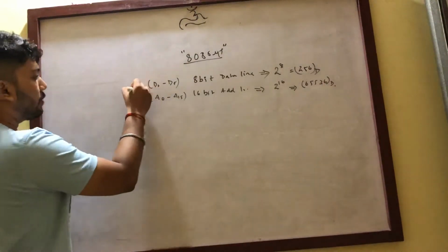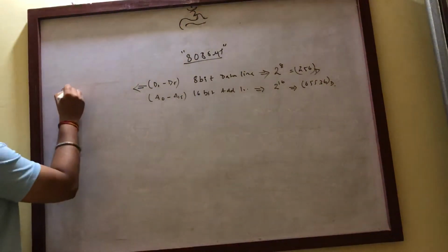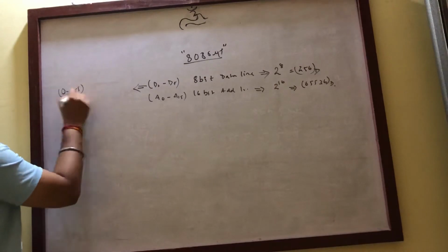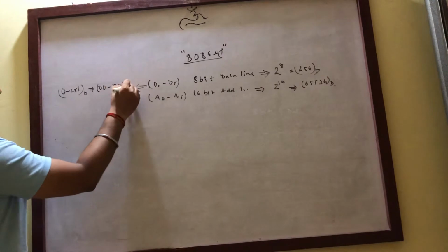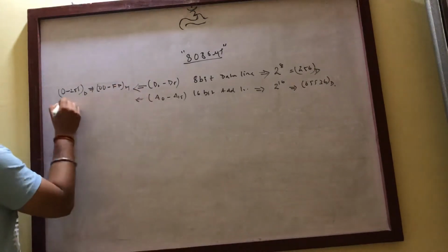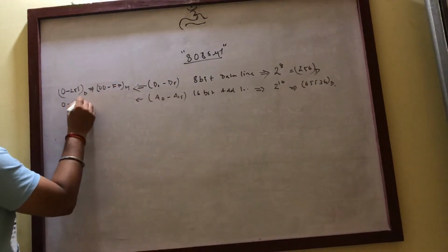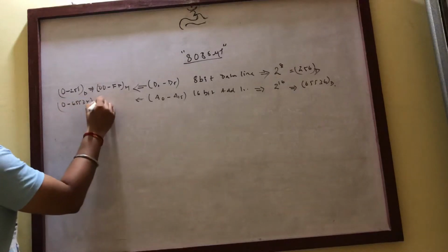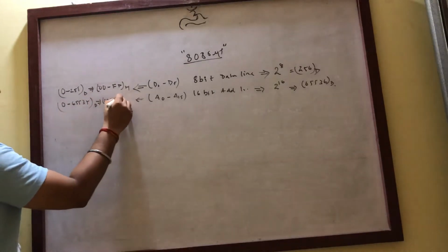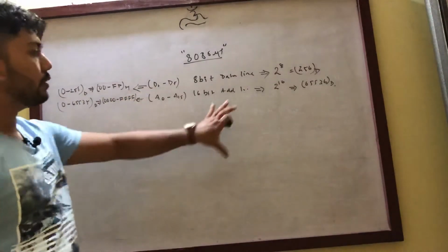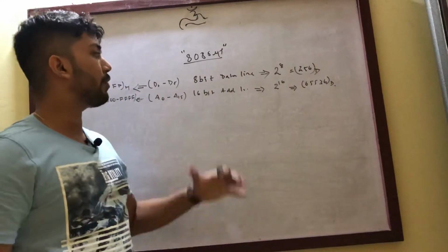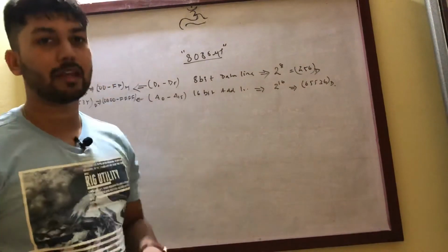So coming to its range, for data it is 0 to 255 in decimal, and that is 00 to FF in hexa. Similarly, for addresses it is 0 to 65535 in decimal, and 0000 to FFFF in hexa. So this is the basic thing about the 8085 microprocessor, in order to understand any type of program that is written.